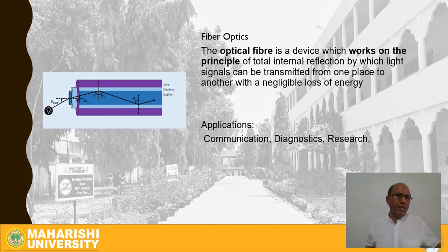In the optical fiber, it is a guided transmission, whereas in the upper atmosphere, in the electromagnetic radiation, in the open air, it is through the omnidirectional radiation process. So anyway, these two are different things. So we are talking here about the communication. So you can say that in optical fiber, your communication is a guided communication. That means the optical fiber is more like a guide, right? Because it directs your optical beam to go in a particular direction. So you will learn about the optical waveguides also during the course of this discussion later on.